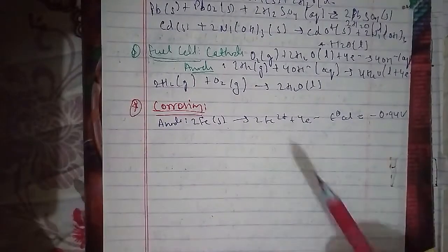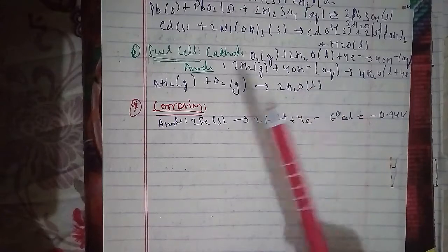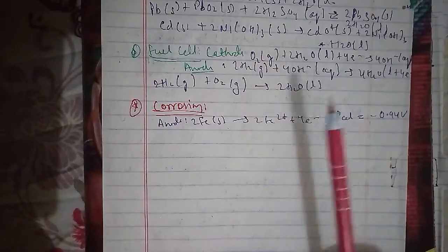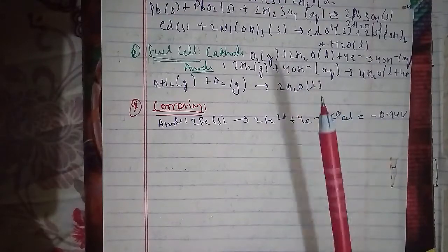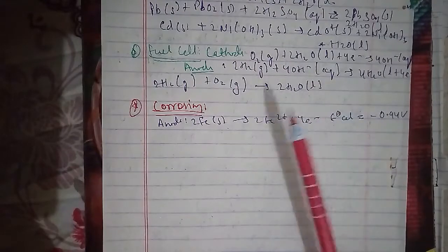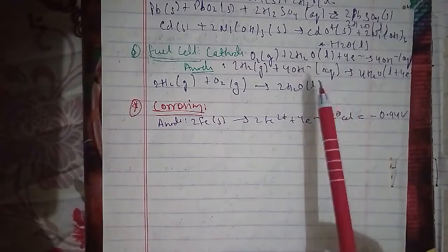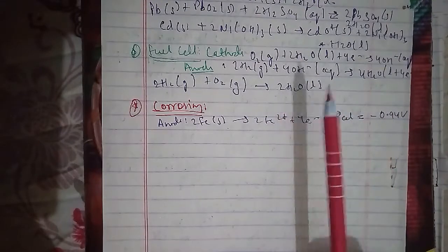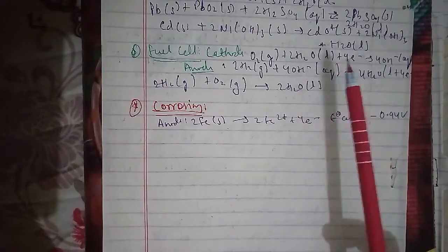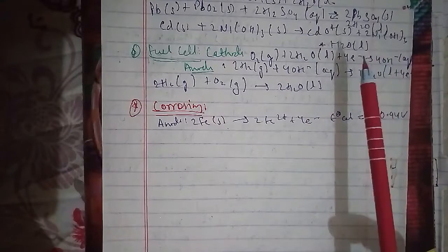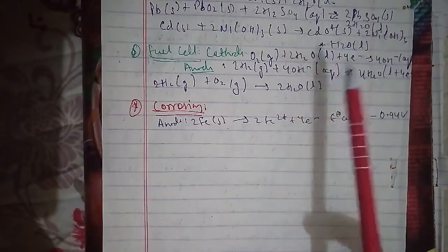The electrons released at the anodic spot move through the metal and go to another spot on the metal, and reduce oxygen in the presence of H+, which is believed to be available from H2CO3 formed by the dissociation of carbon dioxide from air into water. Hydrogen ions in water may also be available due to the dissociation of other acidic oxides from the atmosphere.